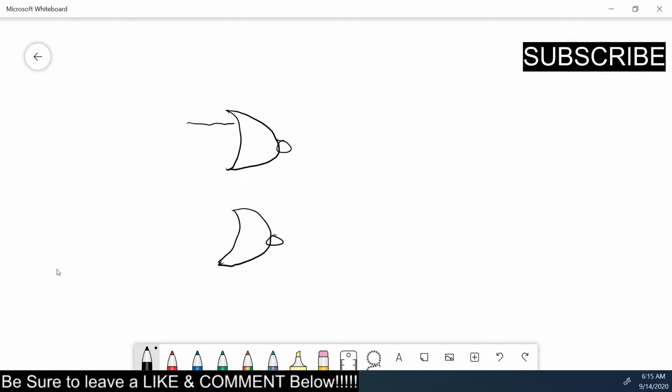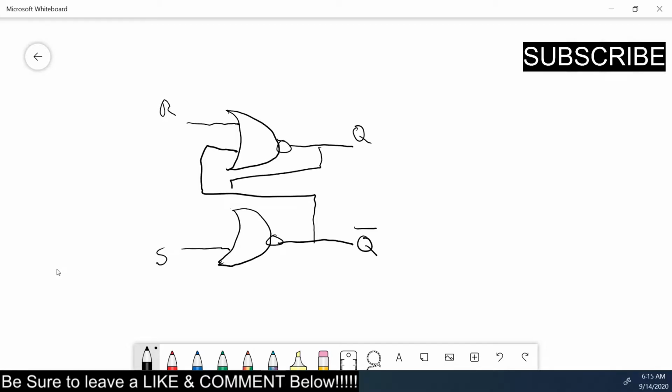So here is your NOR gate, this is your R reset, and this is your set, and then coming off of here is your Q and your Q naught, and then coming off of this one it feeds back into this NOR gate, and coming to this one feeds into that NOR gate.